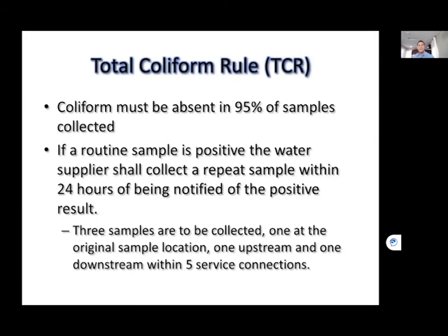Coliform must be absent in 95% of samples collected from your TCR taps. If a routine sample is positive, the water supplier shall collect a repeat sample within 24 hours of being notified of the positive result. 3 samples are to be collected: the original sample, 1 upstream, and 1 downstream, within 5 service connections.